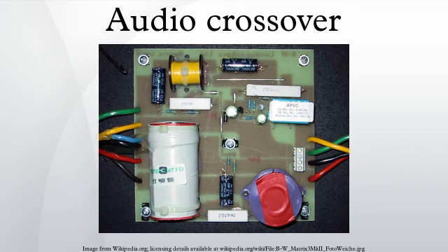In the years before computer modeling, simplistic three-way crossovers were designed as a pair of two-way crossovers, but the advent of iterative design software has taught that this old technique creates excess gain and a haystack response in the mid-range output, together with a lower than anticipated input impedance.